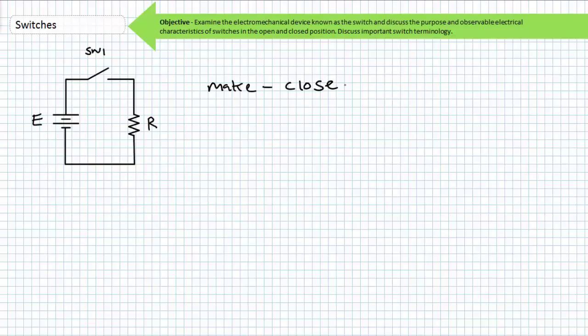Making a connection is the act of closing a switch. Breaking a connection is the act of opening a switch. Recall from the resistance lecture, even air can be considered a conductor between two high voltage points in close proximity. A high power switch must not only be physically larger to accommodate for this possibility, also when breaking a connection, it must rapidly and forcefully rip the moving contacts apart to prevent the electrical arc that forms between the contacts